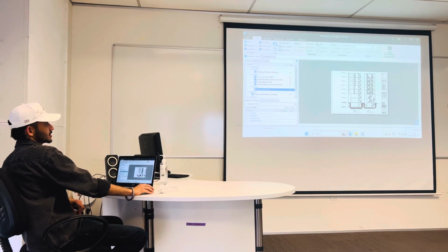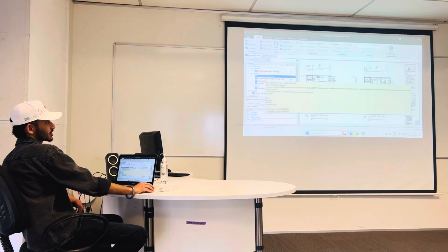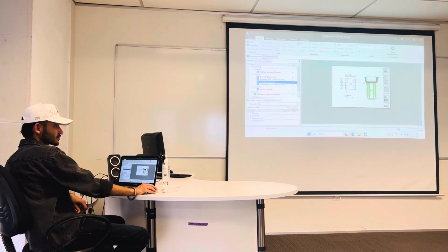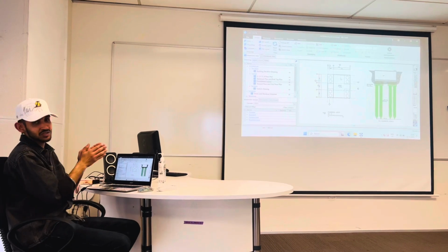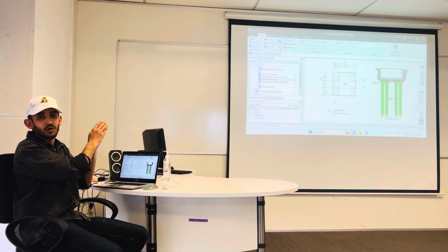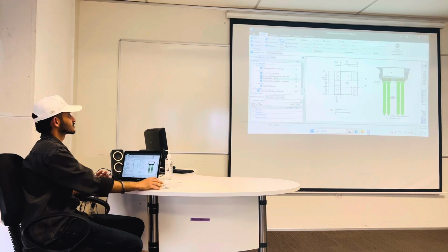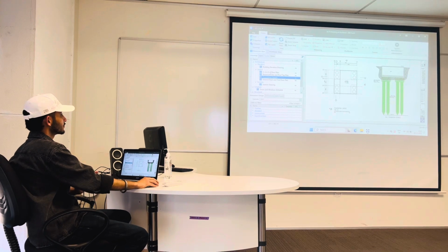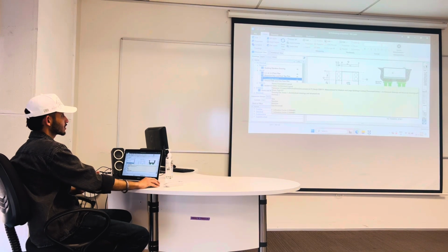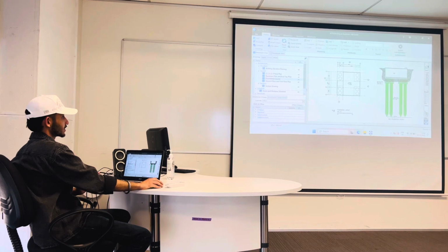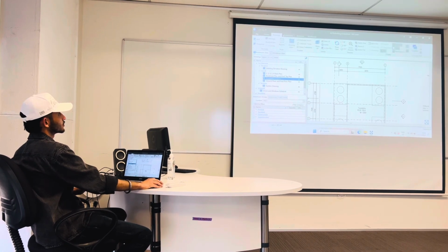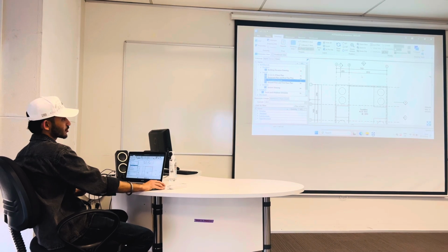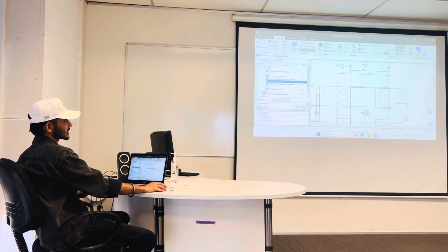First step is to calibrate the drawing according to our real drawings. Calibration means we put the digital measurements according to our real drawings. So for example, we choose the foundation layout and we calibrate this one. So we go to drawings. This drawing is already calibrated, so I'll reset the calibration.